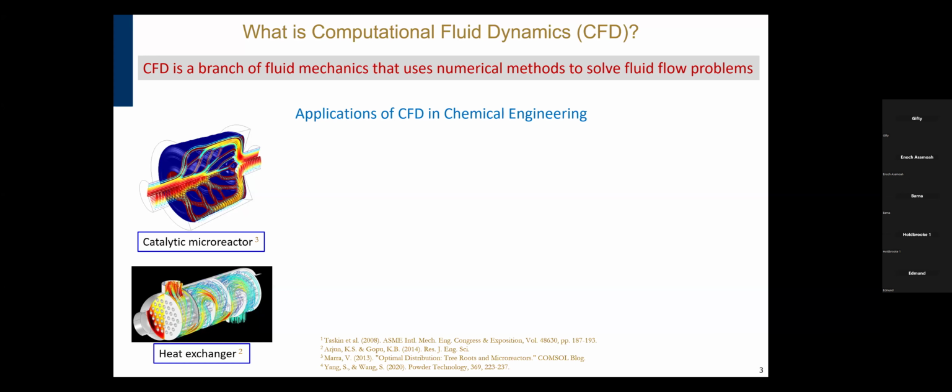On the other end, if you have too little catalyst, your reaction rate is minimal. So the overall goal here is, for a given pressure difference, to find the optimal catalyst distribution in the reactor to maximize your reaction rates.